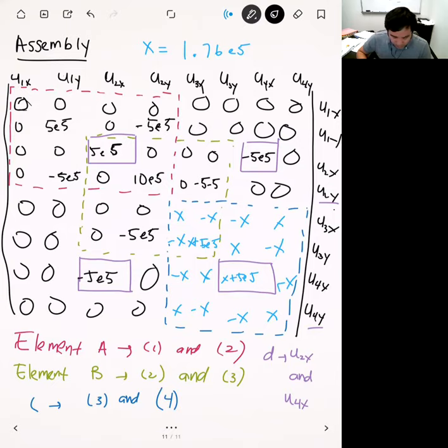Okay. All right. And so this would be kind of like a part B of the problem I would ask you on the exam. Okay. Part C, and the last thing that I would ask you to do would be to modify this matrix for the boundary conditions. Okay. And so for this review, I'm going to do it just kind of in line here, and so I'm just going to erase and add ones. But for the exam, I actually want you to do this as a separate one, just so I can see first of all what your assembly looks like, and I can see what it looks like after you apply the boundary conditions. Okay, so do as I say, not as I do in this case.